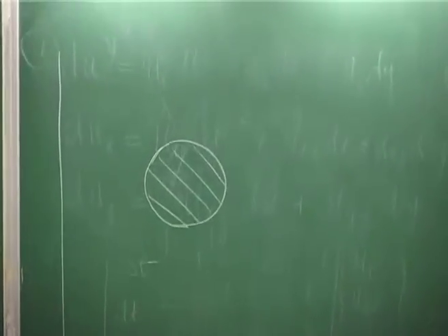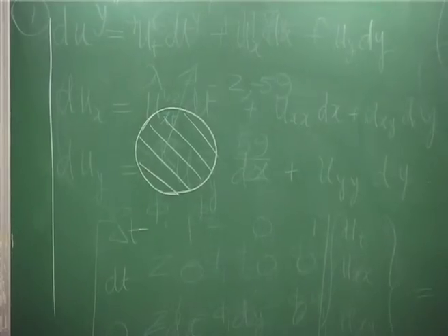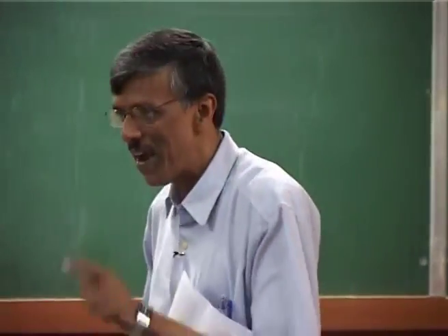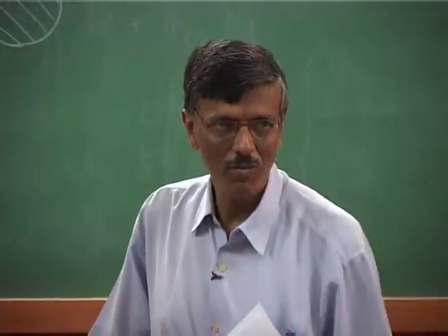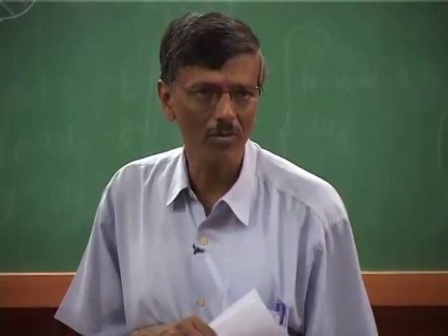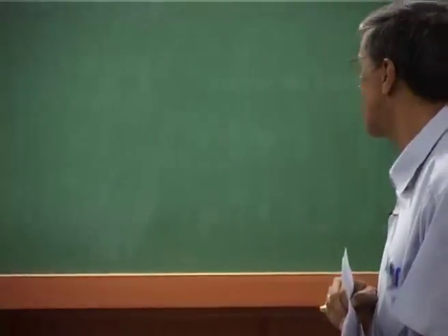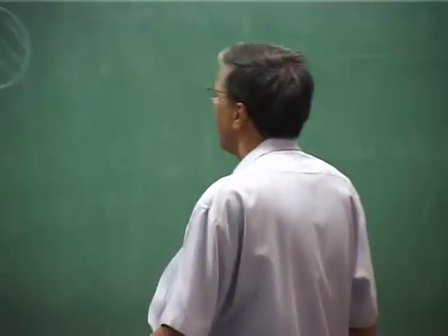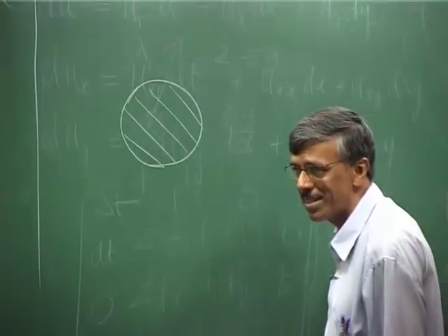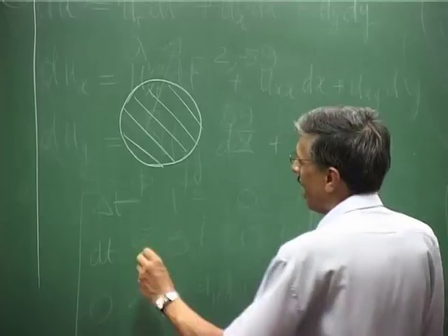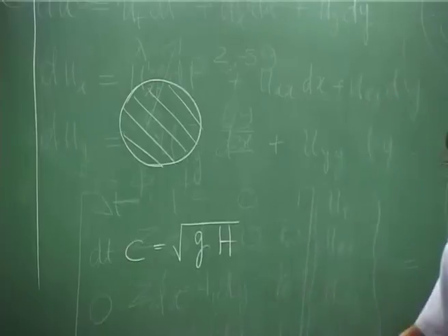straight crest, what should I be looking at? I should be concerned with the phase speed, not the group velocity, because you are focusing on the crest. Crest defines what? The condition of the phase, right? Crest and trough. If you look there, you are very close to the island, so it can be treated as a shallow wave, and then C is √(gh).